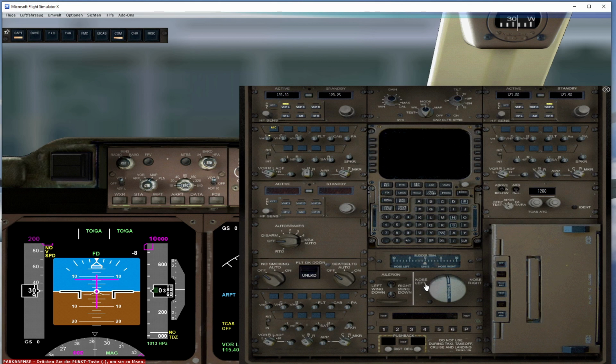VHF right, and then in real life we have some VHF center as well, but it's not on your Fuji. You're transmitting VHF left, which is your primary source when you're talking on the radio, and on the right hand side we have the 121.5, the international emergency frequency, which you should always listen to. So if you're in trouble, you can always hear them.